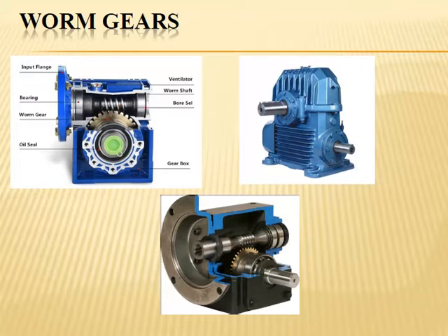The rotating worm splashes the oil. If the rotation speed of the worm is low, meaning less than 750 rpm, an oil splasher is introduced for oil circulation in the gearbox.